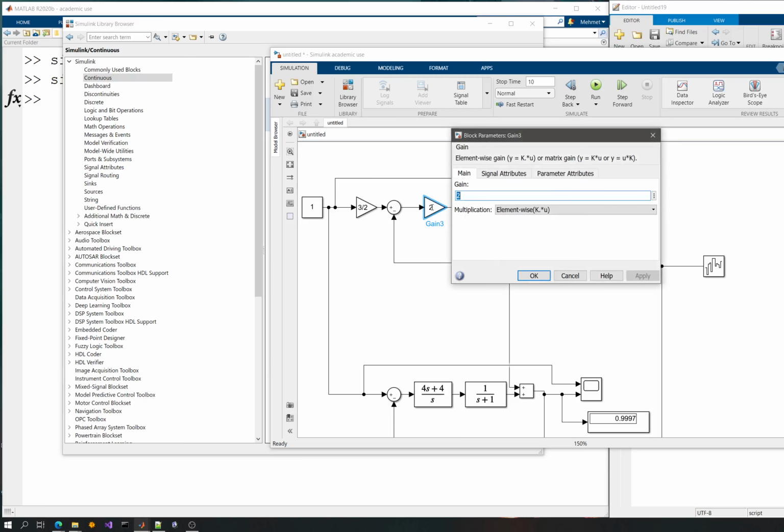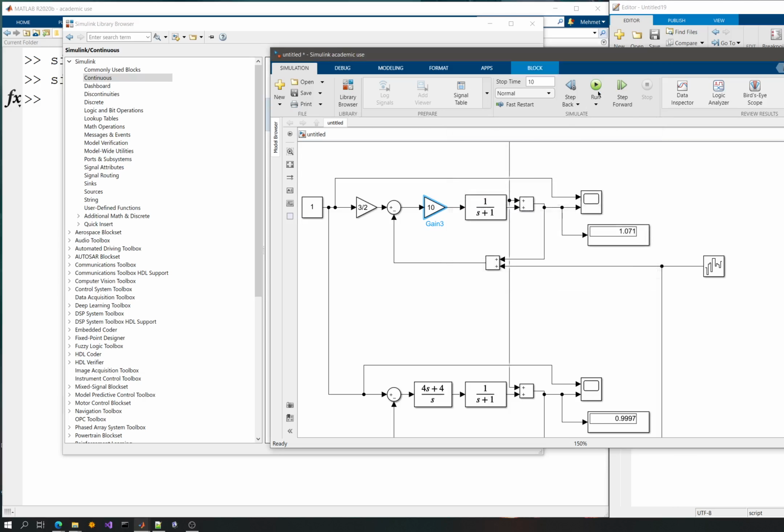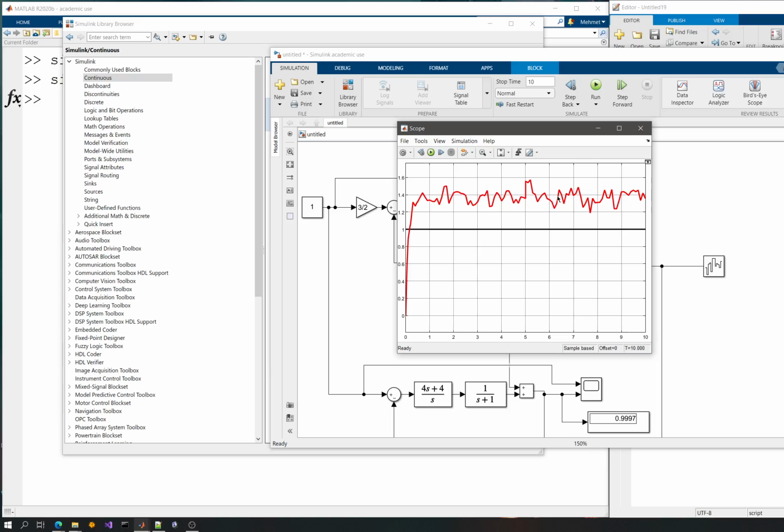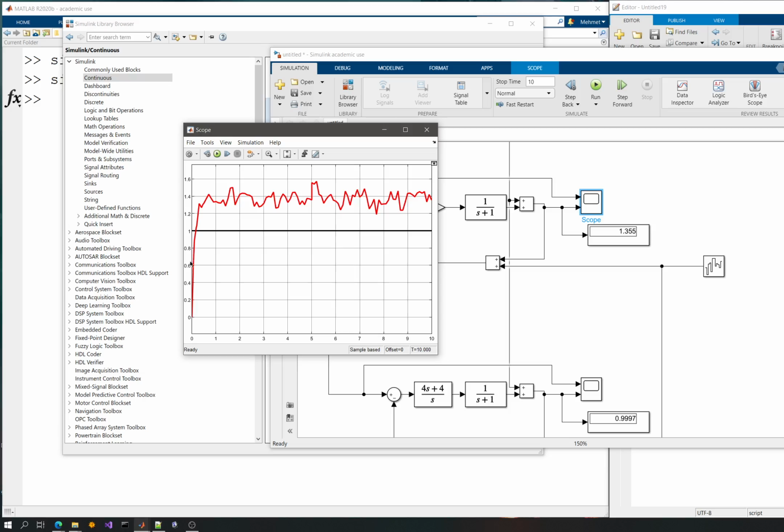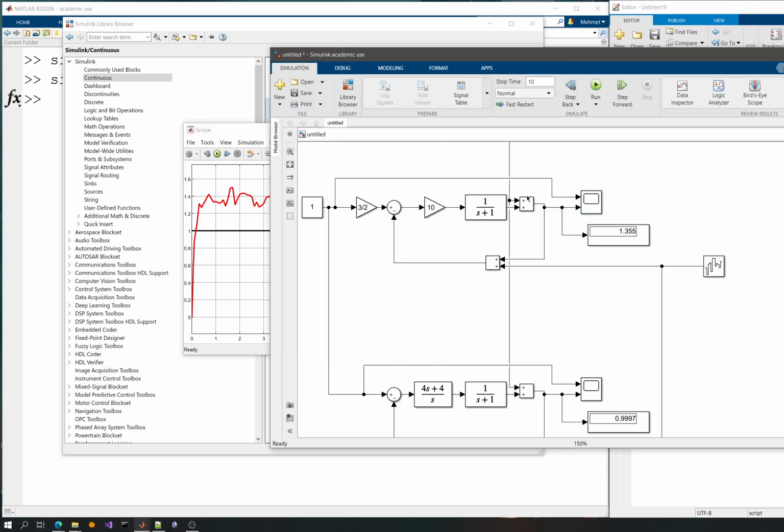But if I, let's say, have a greater gain value and try to stabilize the system, I will see that the performance gets worse, and I'm not even tracking the reference there. And I've talked about this in the last lecture, and I've said that having a greater gain value means that I will also multiply my noise here. And since noise is something that is of high frequency and unwanted, I'm increasing the effect of this. But as you would remember, if I do not have any noise and disturbance, this would have caused the system to track a better output or have some better tracking properties here.